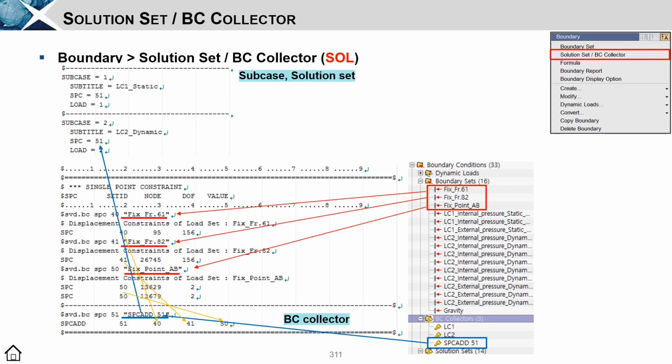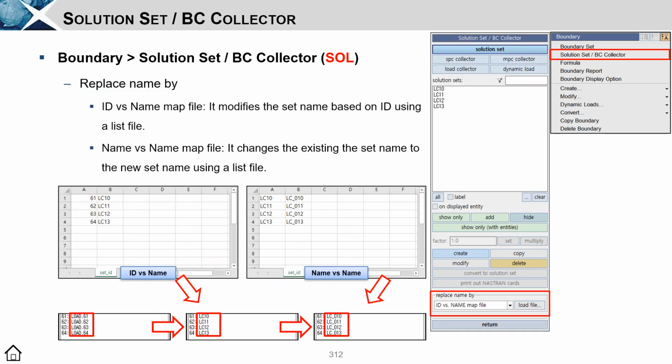In Nastran, when multiple loads are applied, a combination of loads and a combination of constraints should be applied as collectors as follows. Subcase will only bring the ID of this combination. It is equal to the function of set.